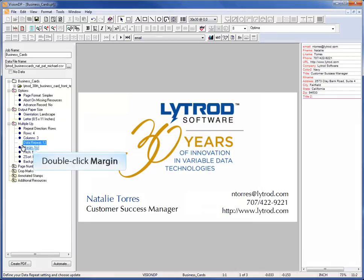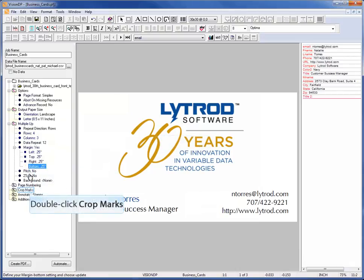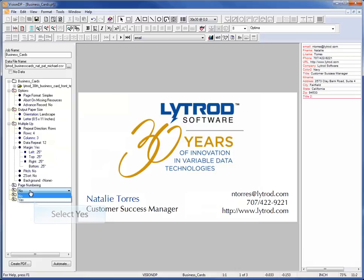To define margin values, double-click on Margins. Select Yes from the drop-down menu to enable more options. Double-click on each margin option and change the dimensions by typing in a new value and pressing Enter. Next, the crop marks can be enabled by double-clicking on the Crop Marks folder. Select Yes from the drop-down menu.